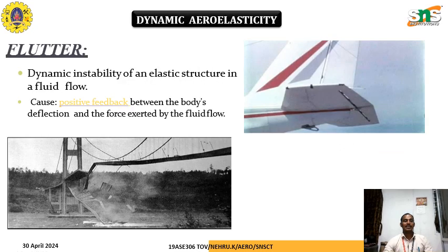Dynamic aeroelasticity produces flutter. Flutter is a dynamic instability of an elastic structure in fluid flow. It causes positive feedback between the body's deflection and the force exerted by the fluid flow. Here we have two examples: the empennage flutter during dynamic instability, and the Tacoma Narrows Bridge, which failed due to the flutter effect caused by aeroelastic phenomena.